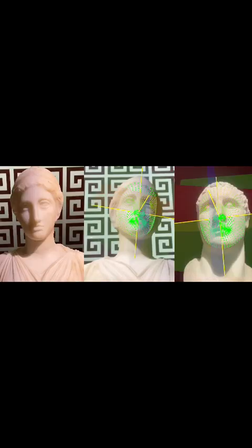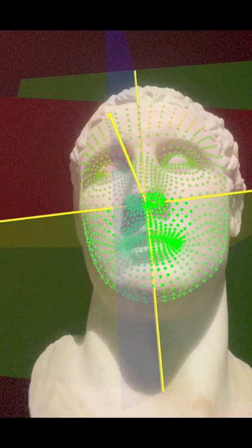Max min points turn color by default at the side of the face with the maximum absolute values. For example, right X equals minus 10 mm, left X equals plus 4 mm. The absolute values are 10 mm and 4 mm. The maximum absolute value is 10 on the right side. Thus a red colored point, over 2 mm, appears over the right side of the face. By turning the button to min, the color of points is turned at the side of the face, this time with the minimum absolute values.